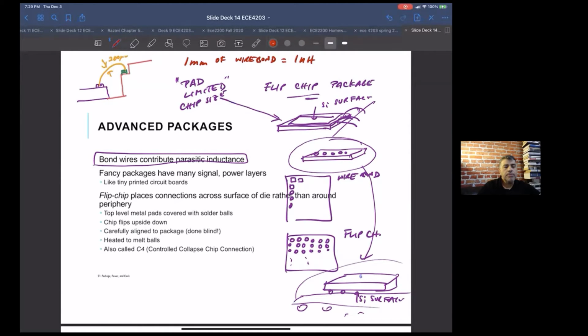So a lot of times when you're designing your own board, this kind of stuff ends up giving you a lot of problems, especially on FPGAs, because you end up having, imagine if you have 10 nanohenry, we'll get into that. If you have 10 nanohenry of inductance that you're trying to get a sharp edge signal through, because a sharp digital edge can have a lot of high frequency components, this much inductance could give you a lot of problems. Okay.